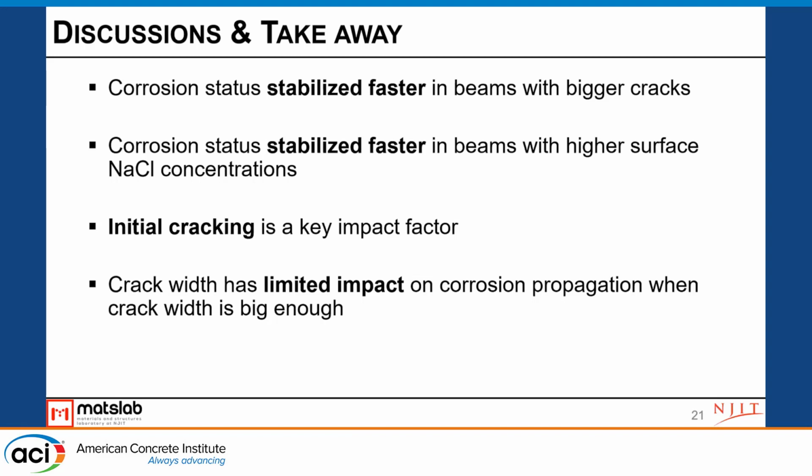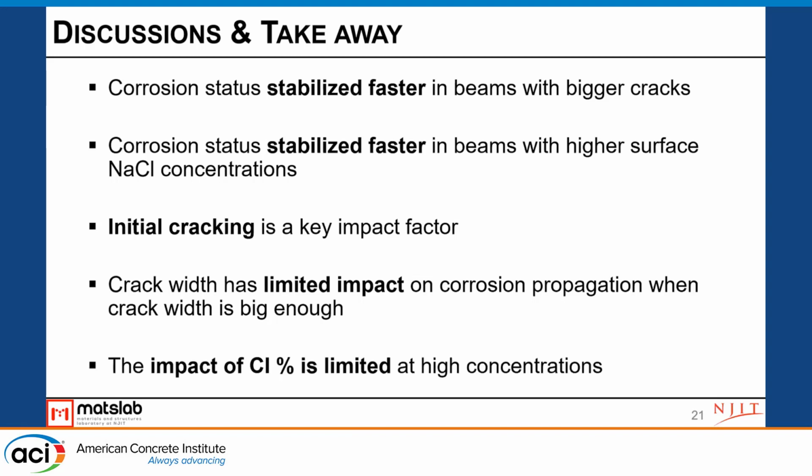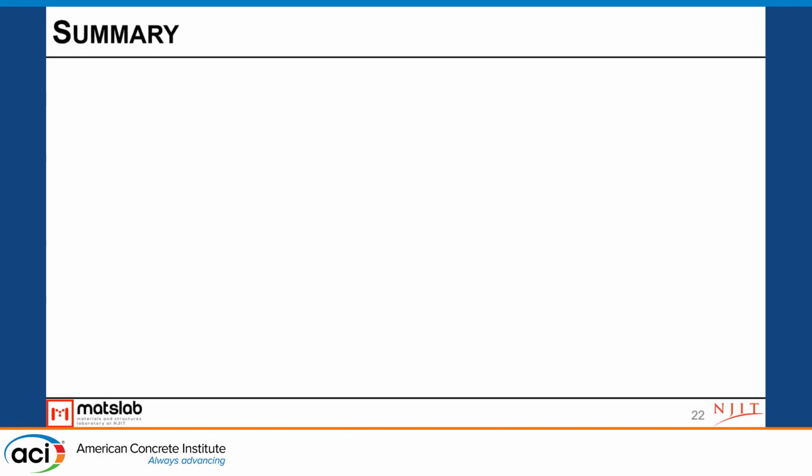Crack width has a limited impact on the corrosion propagation, which is kind of counterintuitive. And also the impact from the surface chloride concentration is limited, especially at high surface concentrations.